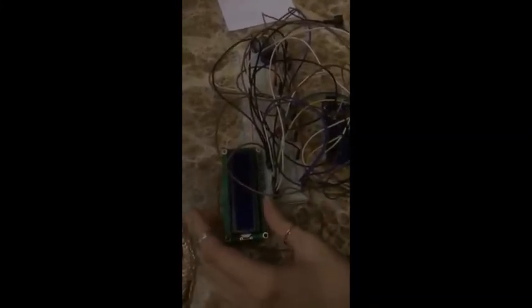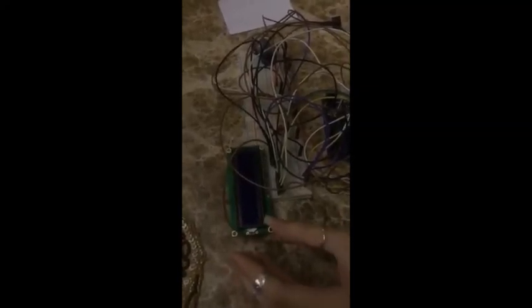Finally, we have the LCD. In the LCD, we faced few problems. The first thing, we didn't have a potentiometer, which is responsible for how bright the screen is. So we connected the pins that are responsible for that to 3.3 volts, and that's pin A. We also connected 4 other pins to the ground. It's the first pin, which is K. It's pin number 16.